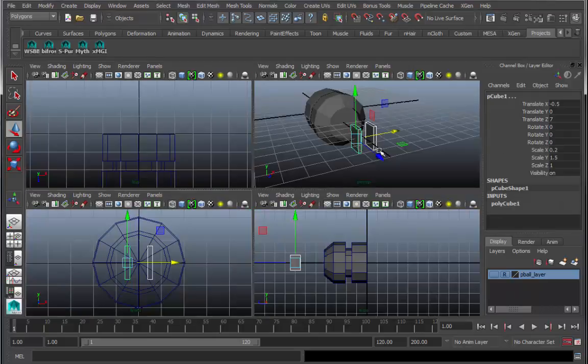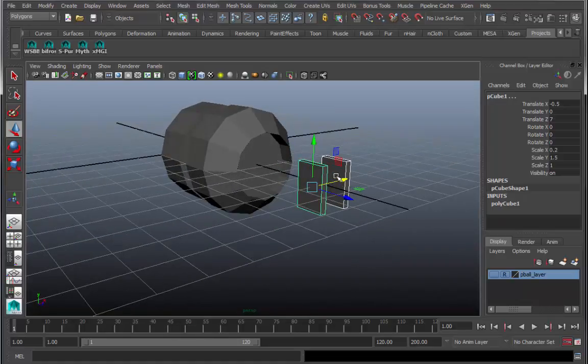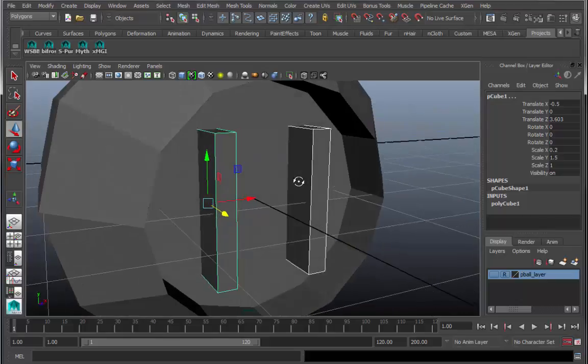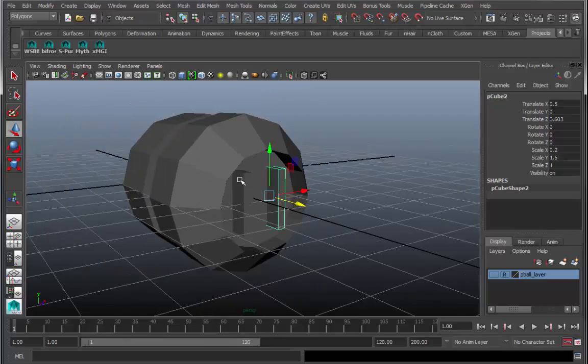Wonderful. So here's the point of this doorknob exercise, as it were. We're going to take these two cubes and push them in and interpenetrate the geometry, because we're going to be using the Boolean operation to take these cubes and dig out that same space. These two similar looking bits of geometry will be digging out holes in the doorknob, so that you have what effectively looks like an electrical outlet from the doorknob handle. Very dangerous thing to have in your house.